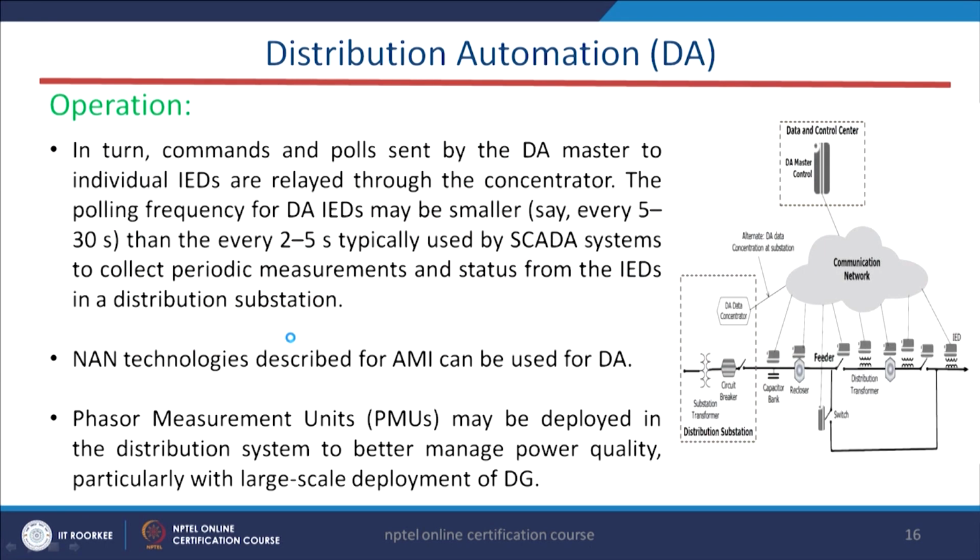That is how the infrastructure, which we have already discussed, works. Here these are the devices: we have a capacitor, a recloser, a distribution transformer, all these equipments and switches. The IEDs will send the data to this DA master control center. Basically this data is sent every 2 to 5 seconds as far as SCADA systems are used.